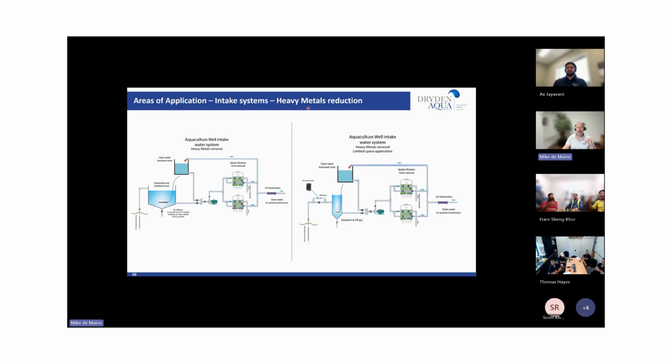In many situations, we use ozone in a very low dose, so 0.2 milligrams per liter. That's a flocculation dose, which helps to flocculate particles. It also helps to increase the zeta potential of the water, in other words, changing the charge density on particles. Quite often, if your particles are fine, they're all very similarly charged, either very high negative charge or high positive charge.